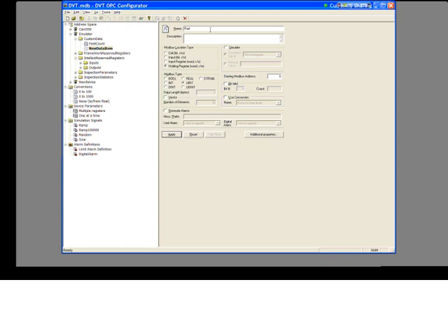This is radius. Radius was written into register 17, and it is a float, so that's a real value. No. I was going to say the D is not a double, is it? No, D stands for, it says double integer, but actually double just refers to the size, so it's a 4-byte. Right, I see that. But there's only one floating point data type, and that's real. Okay.